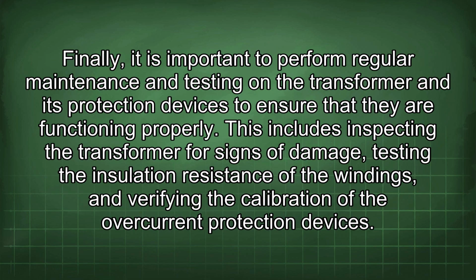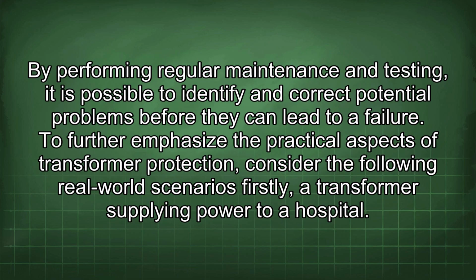Finally, it is important to perform regular maintenance and testing on the transformer and its protection devices to ensure that they are functioning properly. This includes inspecting the transformer for signs of damage, testing the insulation resistance of the windings, and verifying the calibration of the overcurrent protection devices. By performing regular maintenance and testing, it is possible to identify and correct potential problems before they can lead to a failure.